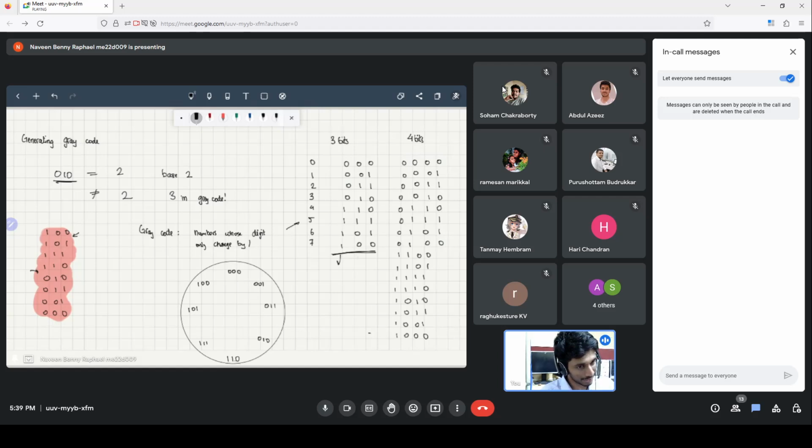And then you take the 3-bit gray code, you flip it, and then paste that at the bottom. And in front of the flipped one, you add ones. Now, that will guarantee that between every bit, there's only maximum one bit of change.